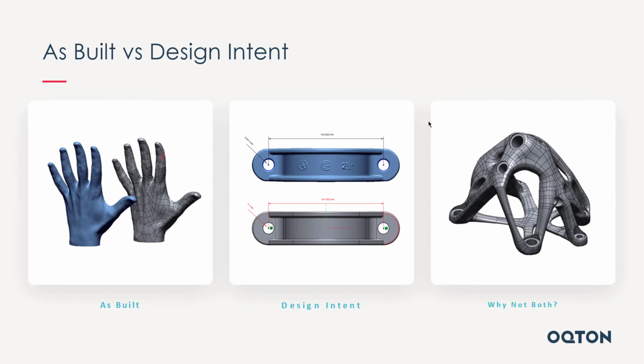So what you need is, I don't want to duplicate the part with the tolerances or error built in. I actually want to create a model of the part that is the design intent, or what it should have been, right? And this is another thing that DesignX does extremely well. That will allow me to model around the part, pull the dimensions, and override them to be what they should be. That way, when I make another one, I'm not stacking the tolerances from when it was made before on top of the new tolerances of what it's going to take to make another one, right?